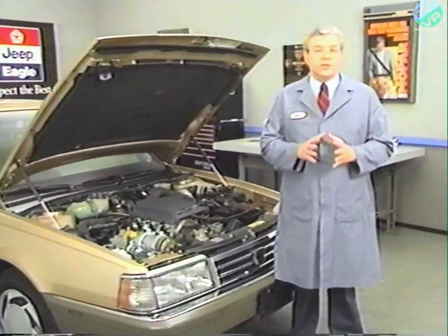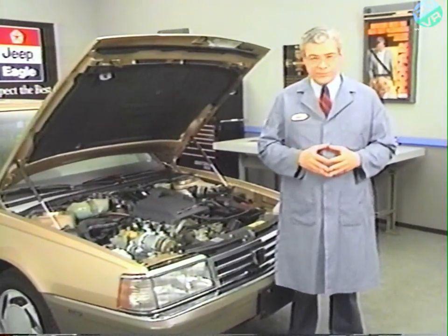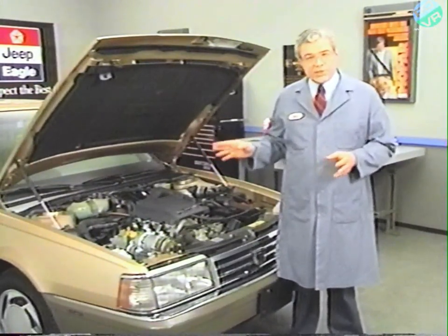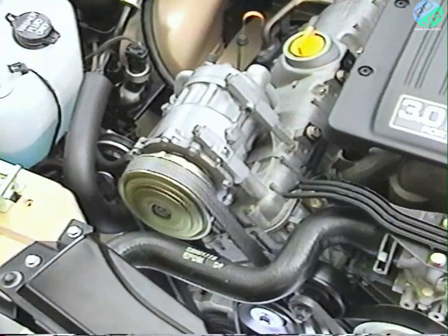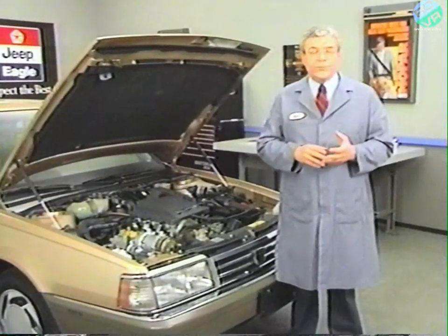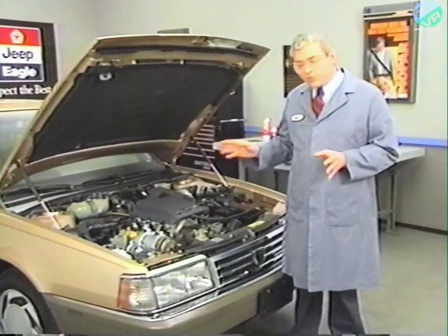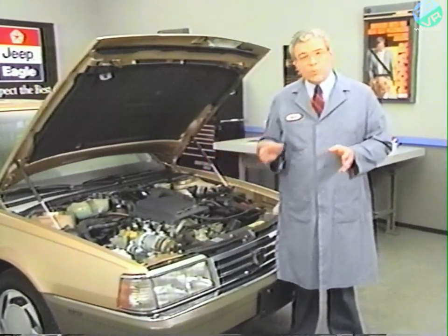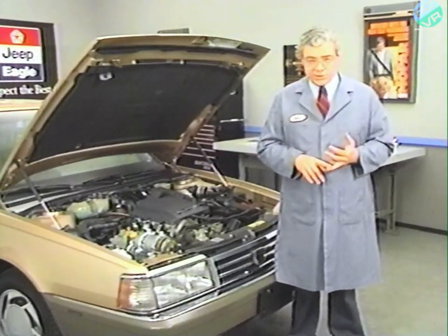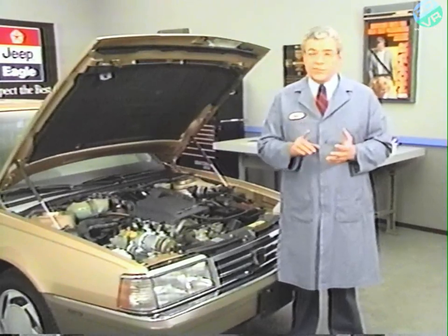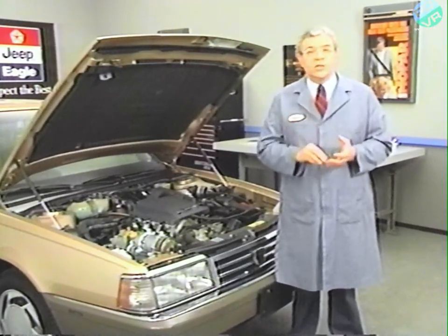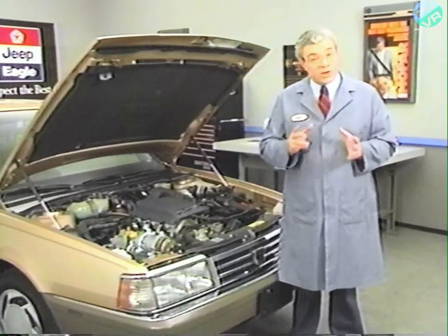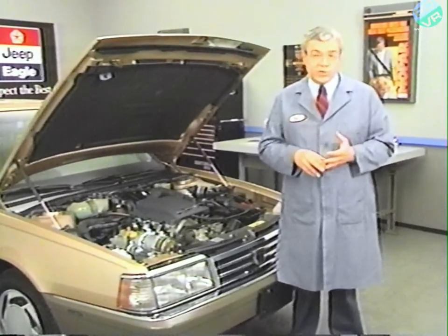When diagnosing no cooling or insufficient cooling, start with the basics, such as checking to make sure the compressor clutch engages. Earlier, when we looked at some of the things that can prevent a compressor from operating, we concentrated on electrical causes. But as mentioned, one of these causes, an open in the clutch cycling pressure switch circuit, can also be caused by low system charge.